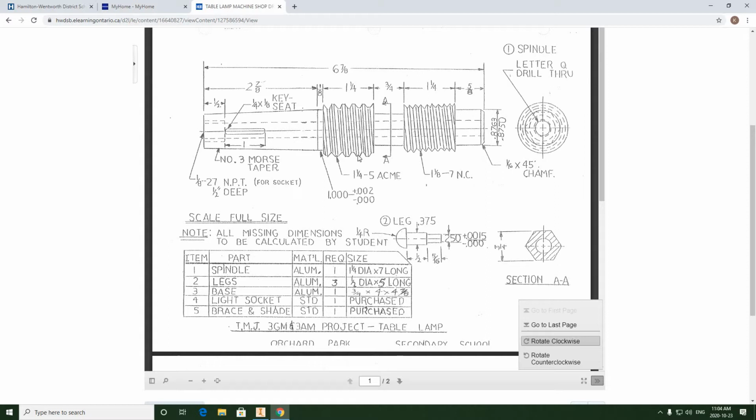So it is shown as 1 1/4 inch diameter, and it says 5. Now, this stands for 5 threads per inch. So basically what that means is for every inch long you measure on a shaft, you should be able to count 5 threads in that inch, right? That's how threads are usually designated, as well as their types.